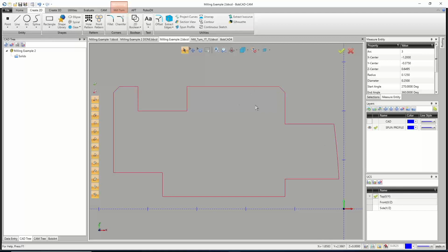So you hold shift, you click, it lights up. Even if this was overhanging this, it would still light up because it ends right there. And a lot of times the problem geometry is not going to be some long line. It's going to be a little tiny piece of geometry. So by holding shift and clicking it and doing it in multiple places, you're ensuring that lucky chain gets found. Because like I said, it doesn't happen often, but after it happens to you once, it's annoying enough that you never want to deal with it again.